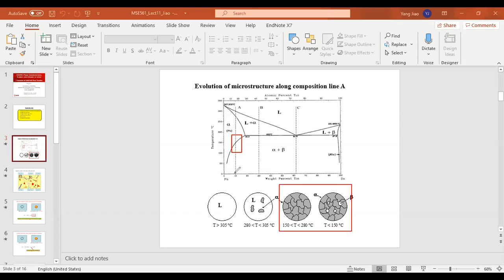But anyway, starting from today, we're going to focus on solid transformations, which also have a lot of interesting topics. We're going to focus on the first one, the simplest transformation, which is the nucleation and growth process in solid transformation. Okay, so if you look at the phase diagram again, we focus on path A. If you start with a liquid state, you're going to go through all of these solidification processes and get this alpha phase field in this large, wide region. If you keep going through these processes, eventually you're going to reach this point, where you're going to have the alpha and beta transformation.